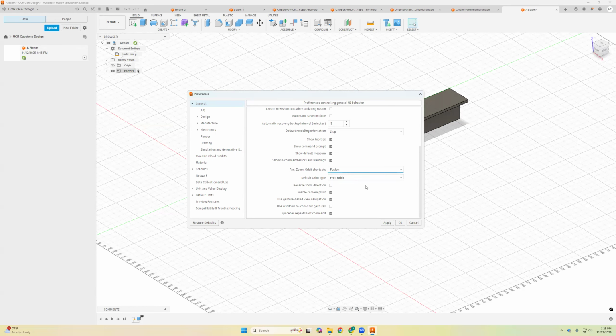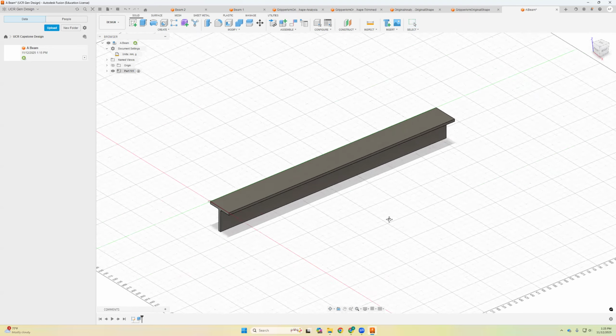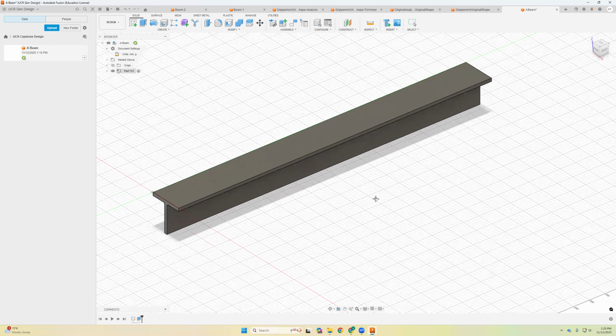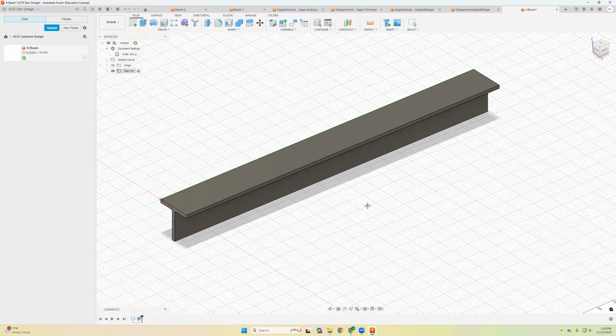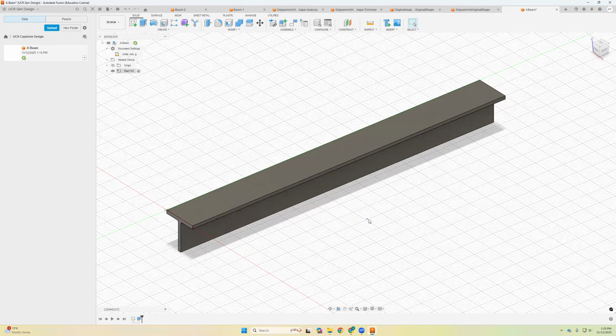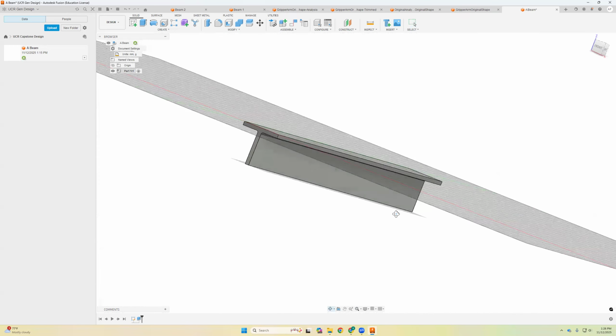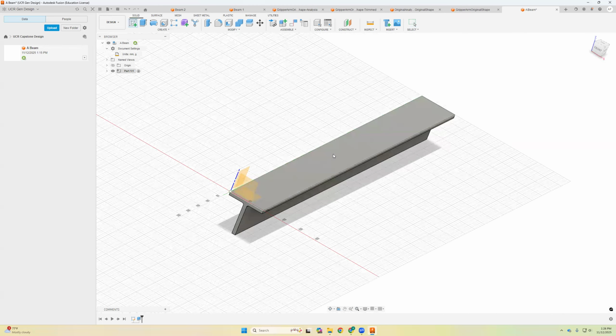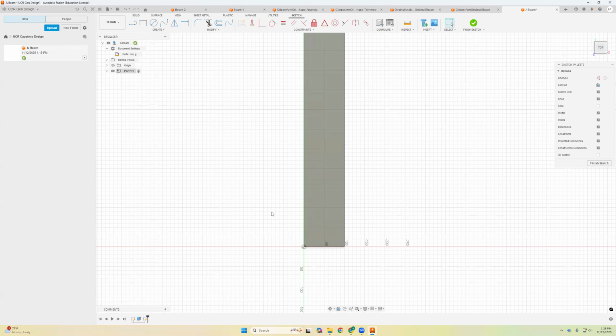I'm okay with Fusion. I select Fusion. And then okay here. So now I can use scroll up and down to zoom. I can use the middle button as a pan, and I can press Shift on my keyboard and the middle button on the mouse to do the rotation. So let's, this cantilever beam, let's say for our design, we also maybe have one slot here,